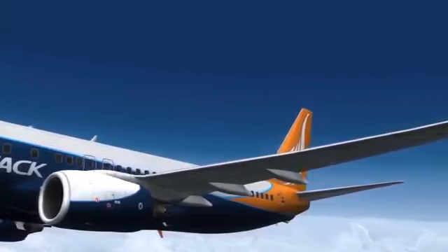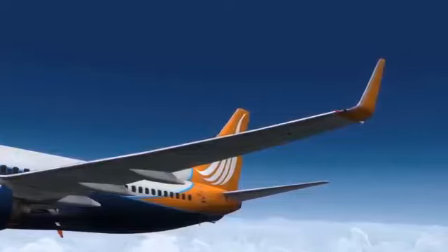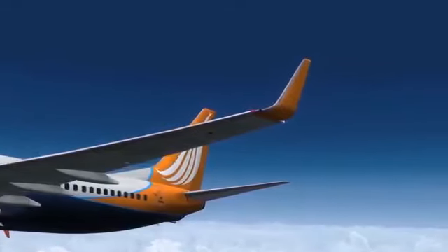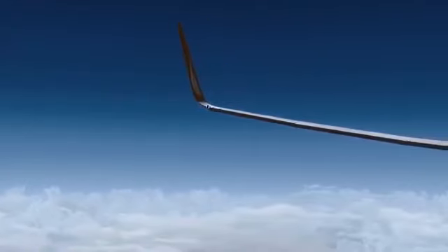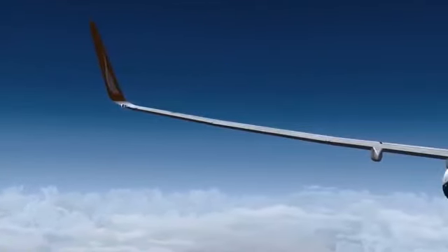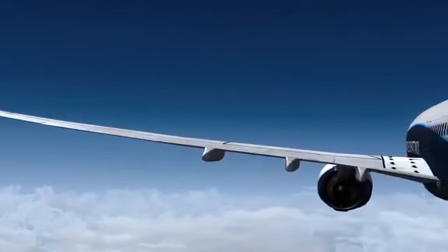The main battery normally only supplies power for APU starting, but is a standby power source when all other power sources are inoperative, such as during a complete loss of AC power if both engines are shut down in flight. We all know that the chances of this occurring are minimal. However, the redundancy must still be built in to make the systems more reliable and dependable.